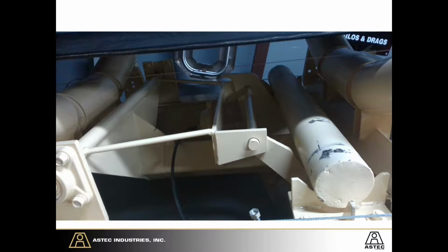As we push through and look at this, we can see here this is the device for the test weight. You can have a test weight here. It gives the operator the ability to do a quick test to see if the calibrations are in. There is some pinch points and things here you need to be aware of. Also, when you do an inspection and you remove these wing guards, this is also areas for material to fall in, so also look for that.